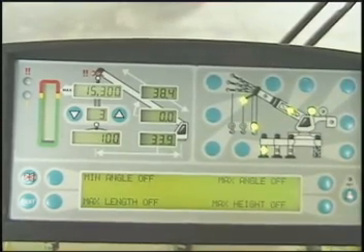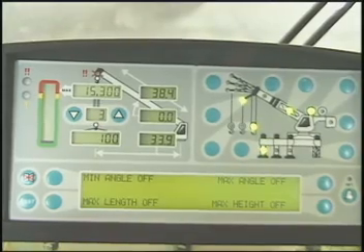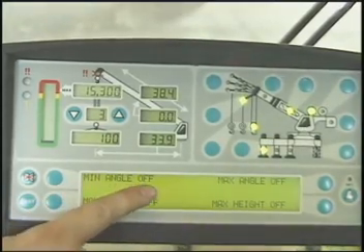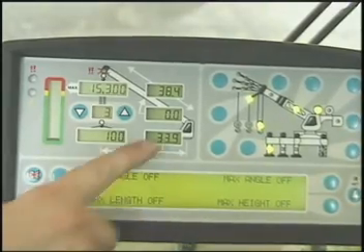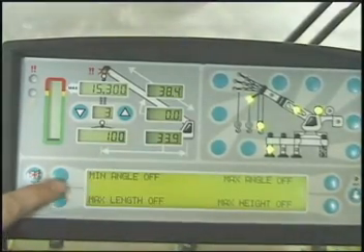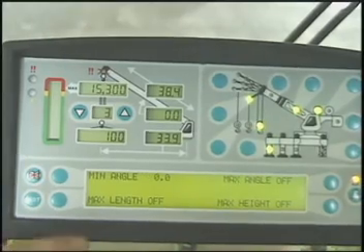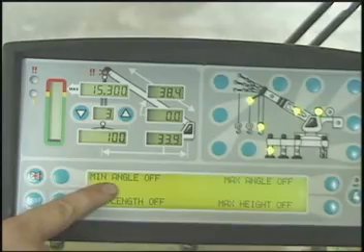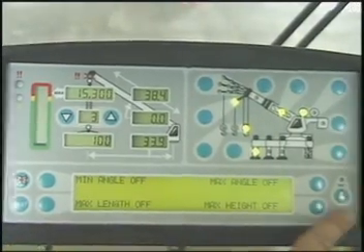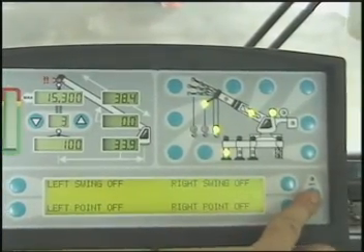For example, to set the minimum boom angle of 0 degrees alarm, with the crane boomed to 0 degrees, press this button. To cancel the alarm, press the button again. To exit the operator alarm screen, simply press the operator alarm button twice.